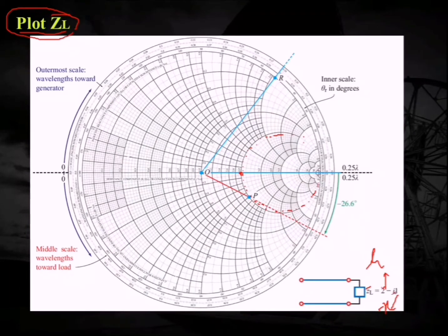But I want my impedance, or this x part, to be equal to minus 1. So I will look at the minus 1 circle. In this part I can see that this is my minus 1. It means my point should lie on this circle also. So definitely here I can see that the 2 circles are intersecting at this point. So this point will be my point corresponding to 2 minus j1.